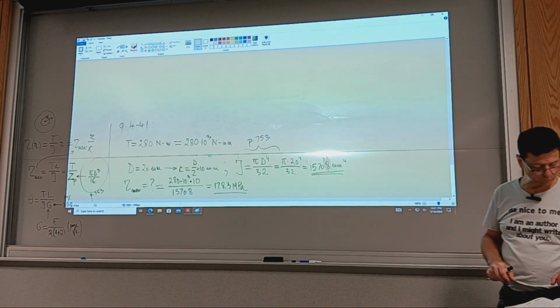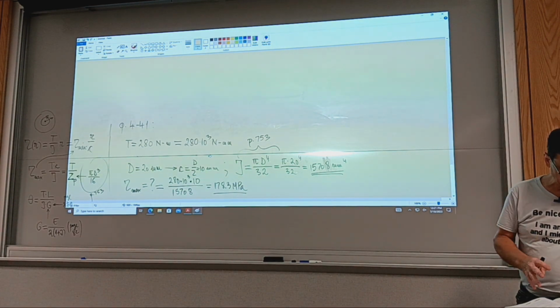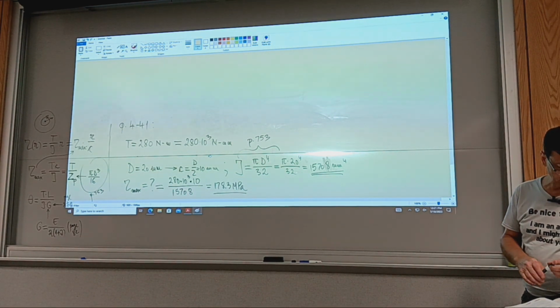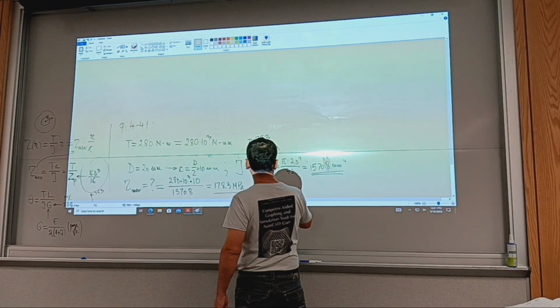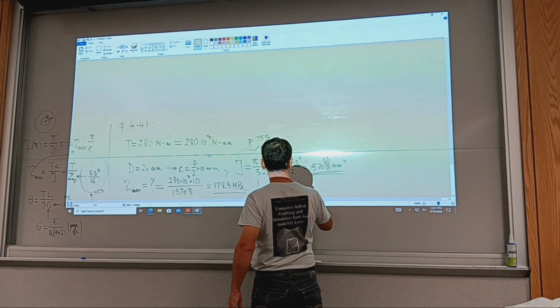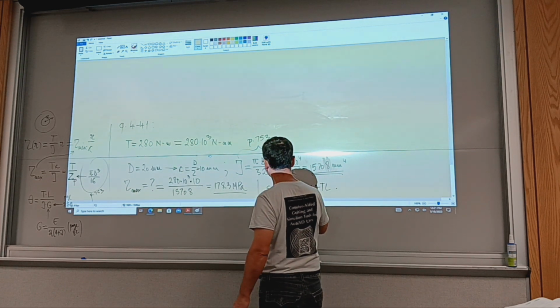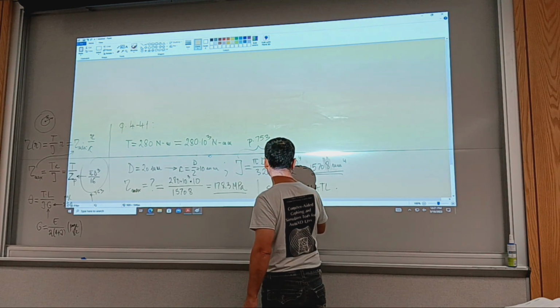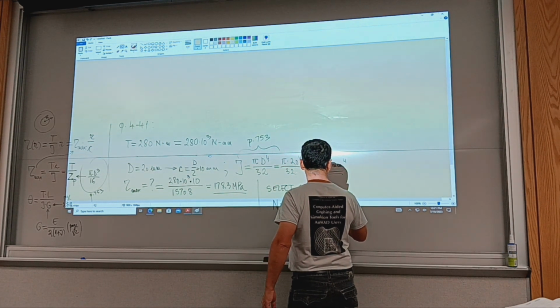For others it would be more than 2, and you also need to make sure you use the right reference property. So select the material, and this will be a carbon steel material. So the design factor is n equal 2. Assume static loading.